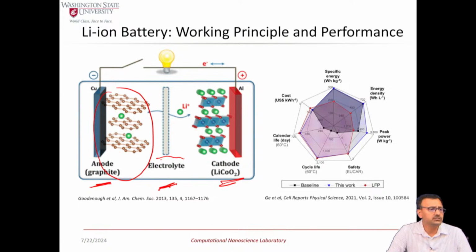Okay. The cathode structure can be made of many different materials. This one here shows lithium cobalt oxide. There is lithium nickel oxide, mixed oxides including cobalt, nickel, etc., and then spinels, lithium manganese oxides, which are cubic structures. And so spinels and layered cathodes are the most popular ones. And the lithium ion basically during the discharge process gets intercalated within that cathode structure until all of the lithium ion is depleted when your battery is completely discharged.